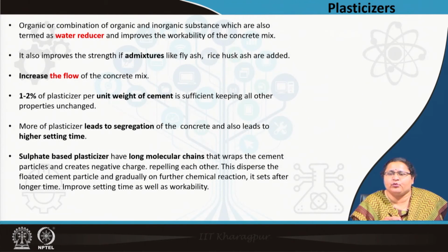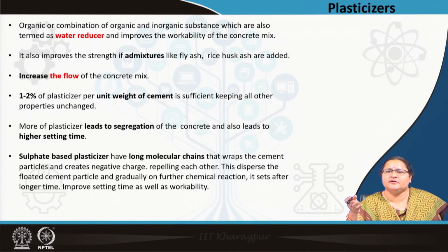They improve the workability of the concrete mix, that is, it will move easier between the network of reinforcements, and these are usually concrete or a combination of organic and inorganic substances. It improves the strength if admixtures like fly ash, rice husk are added. It increases the flow of the concrete.